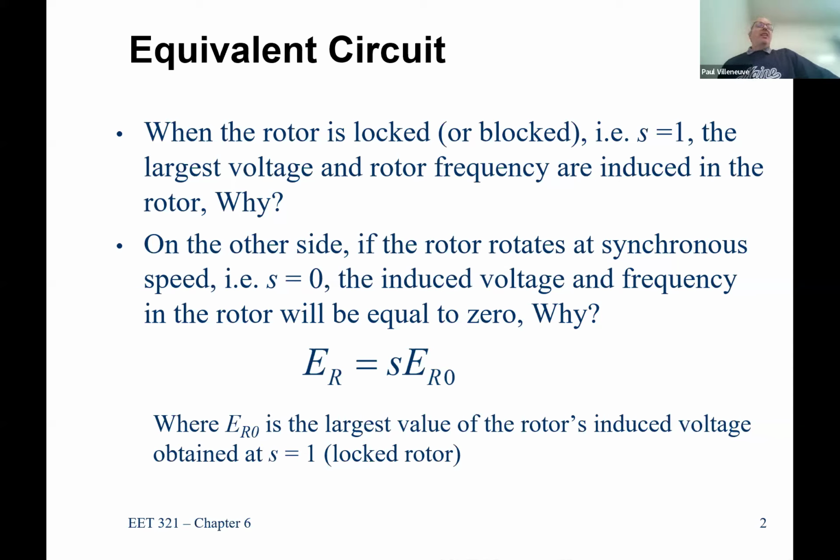And what you're going to see is the absolute highest voltages and frequency. Why is that? Because remember, I have a magnetic field on the stator that's rotating proportional to 60 hertz. The actual rotor itself is not moving. And since the amount of voltage and current that you're going to develop, really it's current that you're going to develop, is based on the rate of change of the magnetic flux, the rate of change is going to be the worst when this is equal to 0, right?